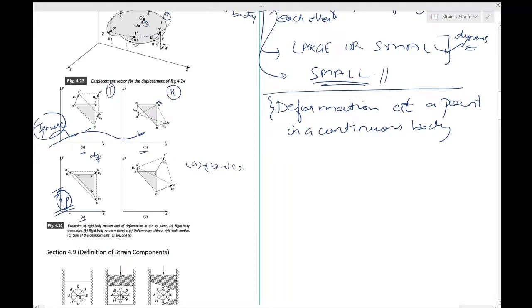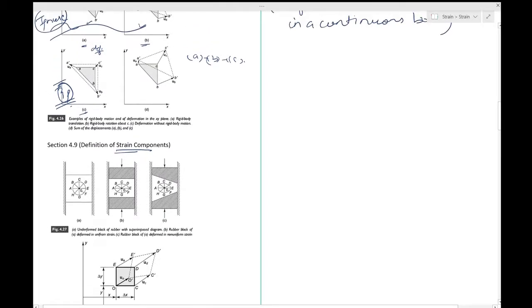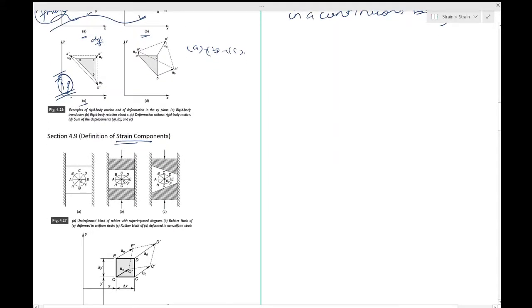And we will continue now to develop a theory of strain, define what strain is, again at a point. Okay. So stress and strain are only relevant at a point. Even when we said, in the previous analysis, stress acting on this plane or that plane, yes, the stress is acting on that plane, but that is only for the sake of direction. The point of reference is something which is already there, which is O in all the cases. Okay. So those are small wedges and small cubes which you consider. So all that gets averaged out.